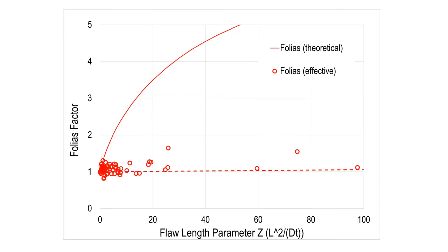Now, I think that for those of you out there that are pipeline operators, this should be giving you a little bit of heartache. I'm assuming that there are times where you send an inline inspection tool down the line, you look at all the flaws that that tool reports, and you do a failure pressure calculation for each one of the flaws, and then you would come up with a dig list.